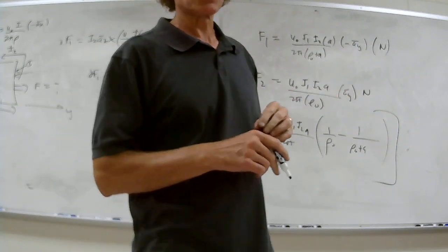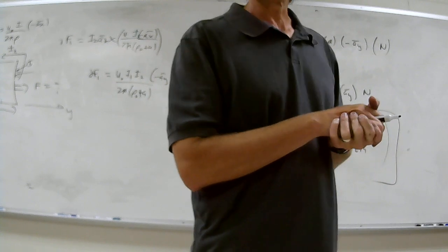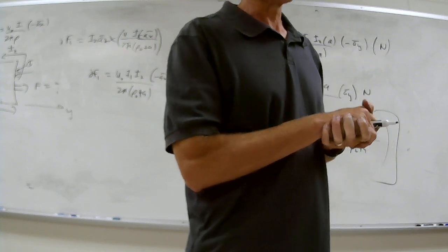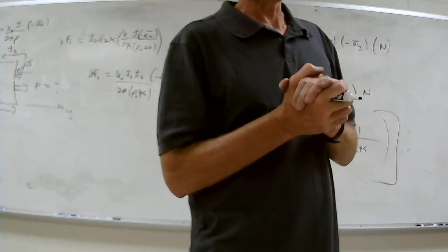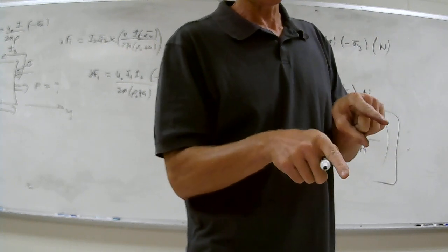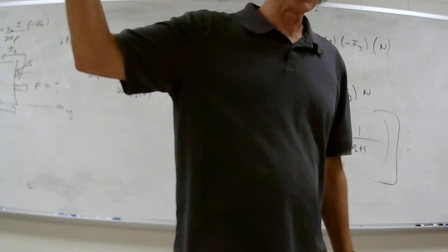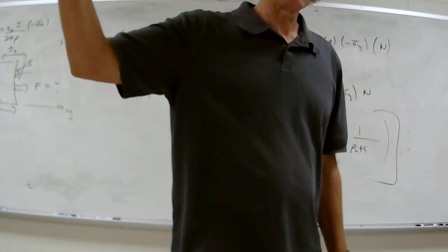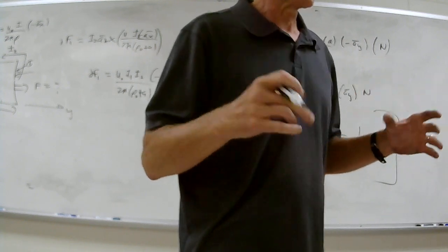And the one thing I'm cautioning you on, when you're doing things with electromagnetics, anytime you have large capacitors discharging a lot of current, try to estimate the peak current values and then calculate the differential forces, because we had wires whipping around when we were discharging this. I didn't expect that. I never had this secured.